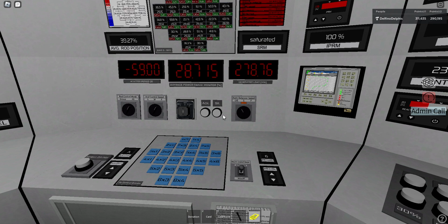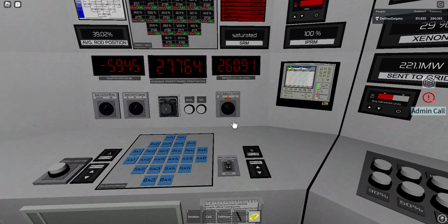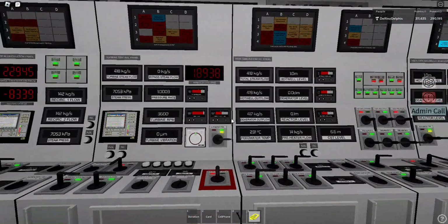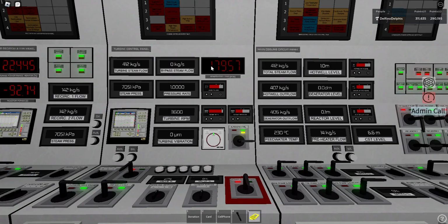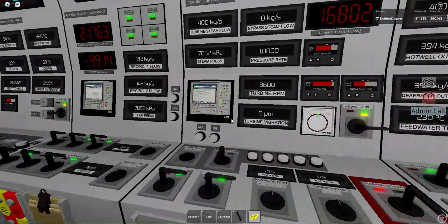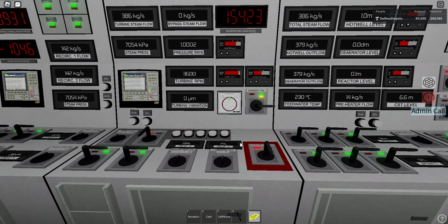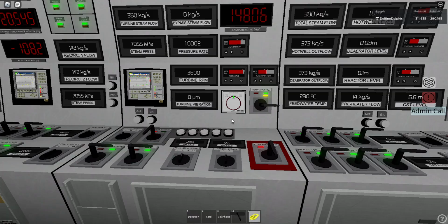When there is this announced offsite disconnection, you have a few minutes to prepare. So this is basically what you want to do. You want to reduce your power immediately. And let's see how our load looks. It's still above 100 megawatts, so it's too much.